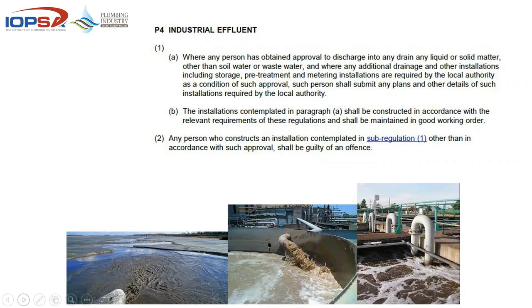Example I like using in this case would be, we have got a Willard batteries in Kebega. So if they charge, or when they charge these batteries, there's acid involved, etc. You cannot discharge that acid into the drainage system and then into the municipal sewer. Likewise, there'd be tanneries, there'd be other different types of industrial processes. Then they need to end up going into like the pre-treatment. They'd be in ponds or they'd be treated before they actually get discharged into the municipal sewage reticulation.